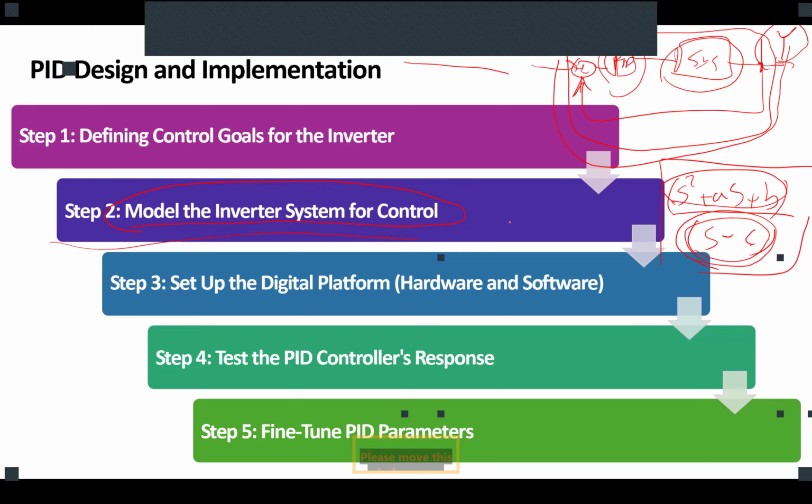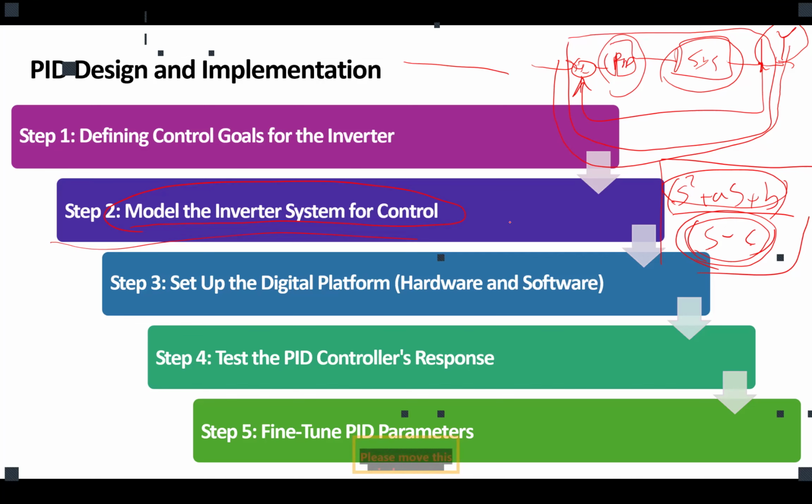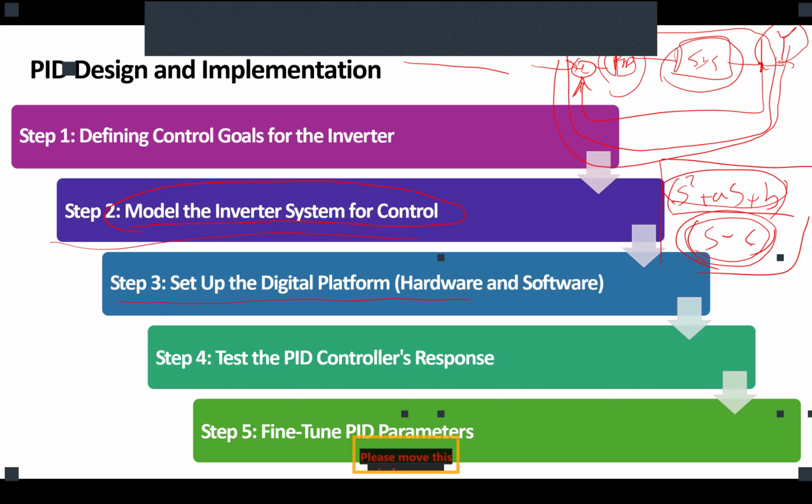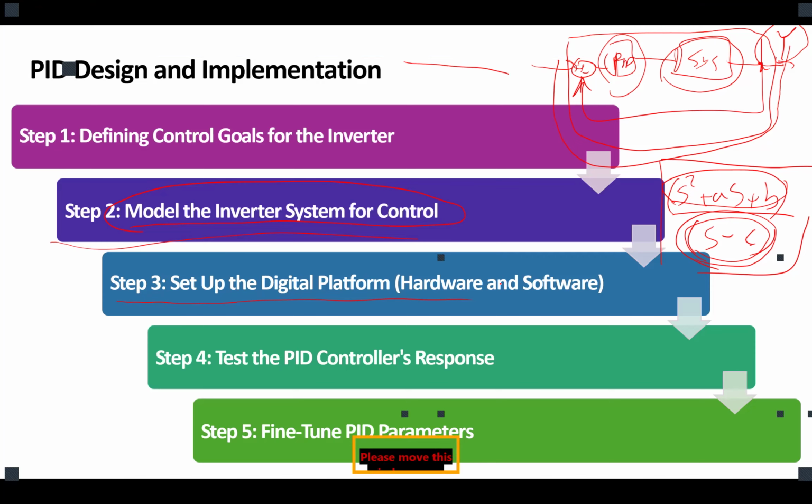When you define the model of your system and you find out where not to go because of instabilities, and you know what's going on in your system, the next step is to set your values. Now you know the optimum KP, KD, and KI. If it's digital, it's directly applied to the system.